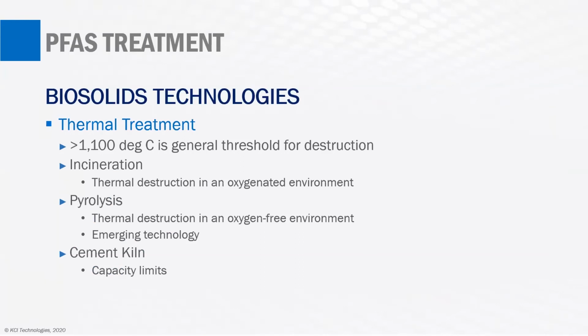And so some of the approaches that could be taken for thermal treatment of biosolids would be incineration. So here we're talking about thermal destruction in an oxygenated environment. And incineration is not a new technology. It's been proven and it's been used a lot. But one of the things that will become a consideration for deploying that for PFAS is, there's fewer incinerators in operation now than there were 40 years ago. And there's a reason for that, because people don't like them in their backyards, because there's still some environmental issues related to incineration. And of course, there's a lot of costs and so forth. And so the idea of trying to turn around opinion about incineration and deploy it at a large scale for PFAS treatment is going to have its challenges.